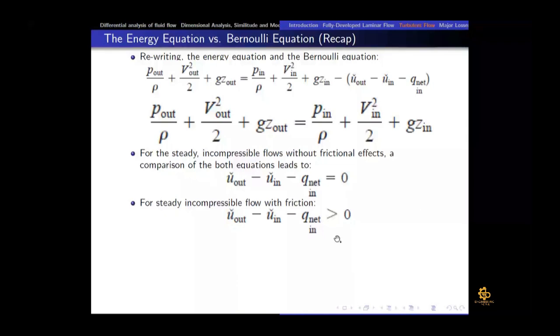It is analogous to how in winters we usually rub our palms against each other. That is one way of converting frictional energy into thermal energy. That concept also happens in fluids due to the interaction of molecules. So there is some conversion of flow energy into thermal energy. This term represents the loss of useful energy that occurs due to friction. It means that the energy is not being destroyed; it is being changed into thermal energy, which means the flow temperature should increase a little bit.